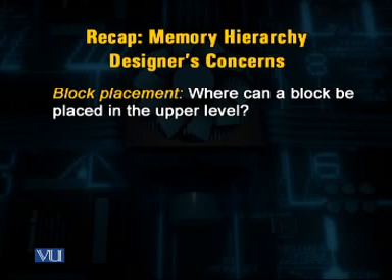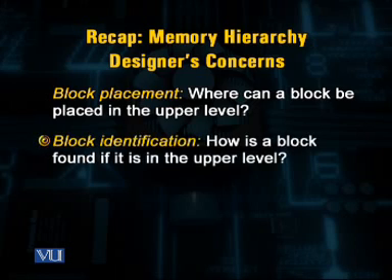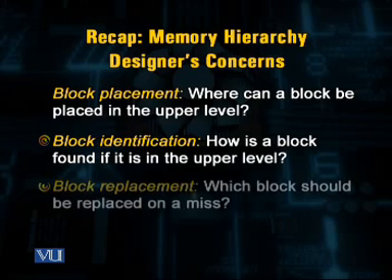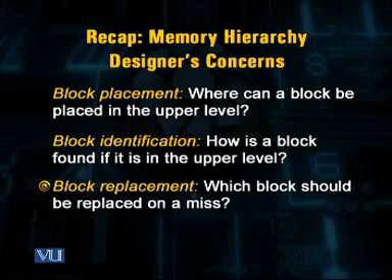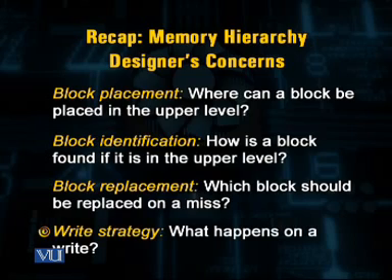The second question is regarding block identification, where a designer wants to know how a block is found if it is in the upper level cache or not. The third question deals with block replacement, that is, which block should be replaced when a miss occurs. And the fourth question is regarding the write strategy, which deals with what happens on a write.